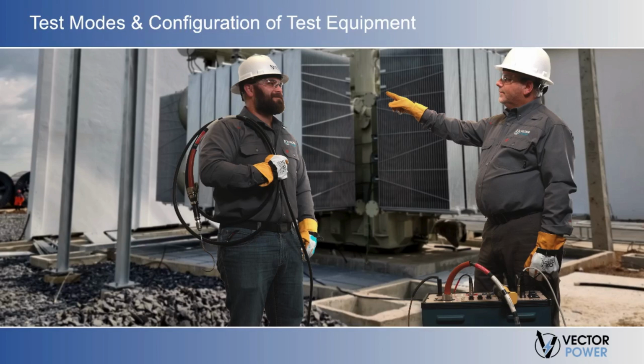Now, to help us in understanding the operation of the test set, it's important to consider the relative positions of the test set's power source, for example, the 10,000 volt winding of the test set's high voltage transformer, the measuring circuit, and the specimen being tested with respect to the test ground and the low voltage measurement leads or measurement channels.